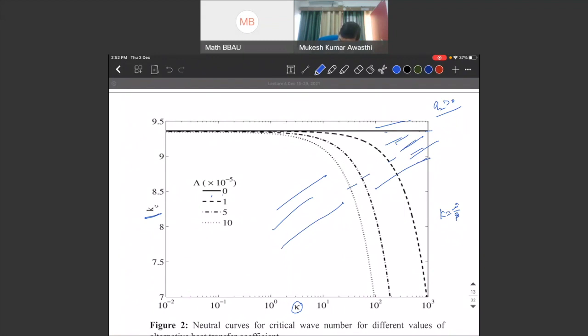Actually, when water is in the upper region and vapor in the lower region, and heat transfer increases at the interface, in the vapor side there will be more evaporation, and in the water side there will be more condensation. Vapor comes in the side of water and will condense. Water goes to the vapor phase and evaporates. In those cases, the perturbation velocity will be very slow, and so the instability delays. And that is the basic thing about the stabilizing impact of heat and mass transfer.